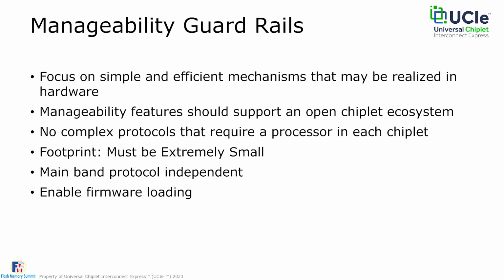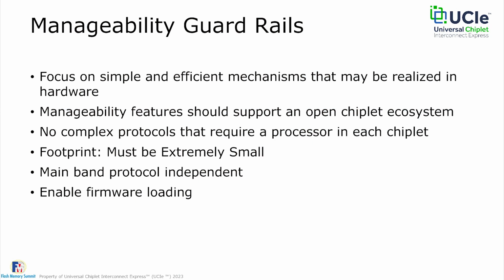We don't want any complex protocols, right, which require a powerful processor on the chiplet. If the control processor there is going to be bigger than the chiplet functions provided, that's not going to be very useful either. So we want it to be lightweight. And then the footprint, both the hardware and the software, needs to be extremely small. To your point, it cannot be like this massive hardware which gets tacked on to every link. That's not going to be very fruitful.